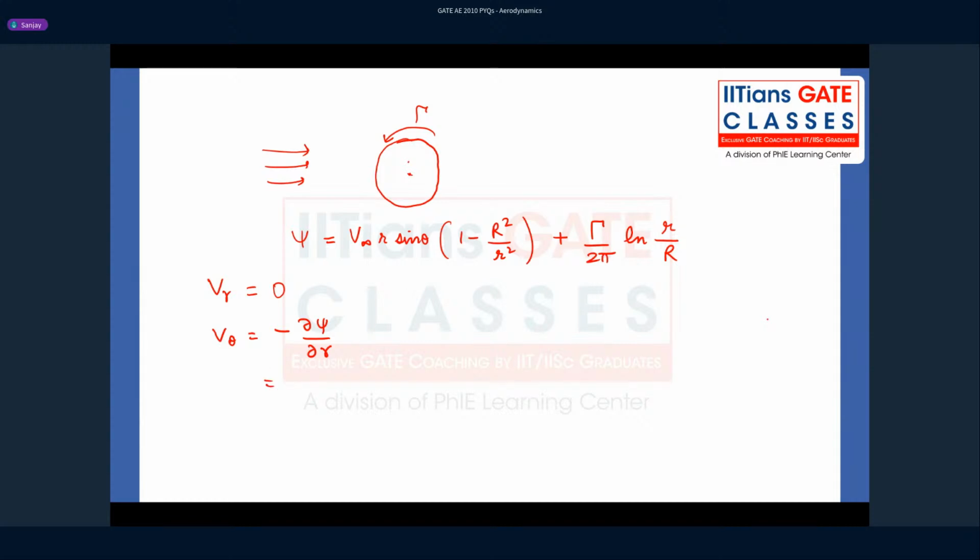Okay, so just differentiate it. What will you get? Minus v infinity sine theta into 1 plus r square by r square, minus gamma by 2 pi. Differentiation of ln is 1 by r into 1 by r, right? So this gets cancelled out, and you want to find it at the surface of the cylinder.